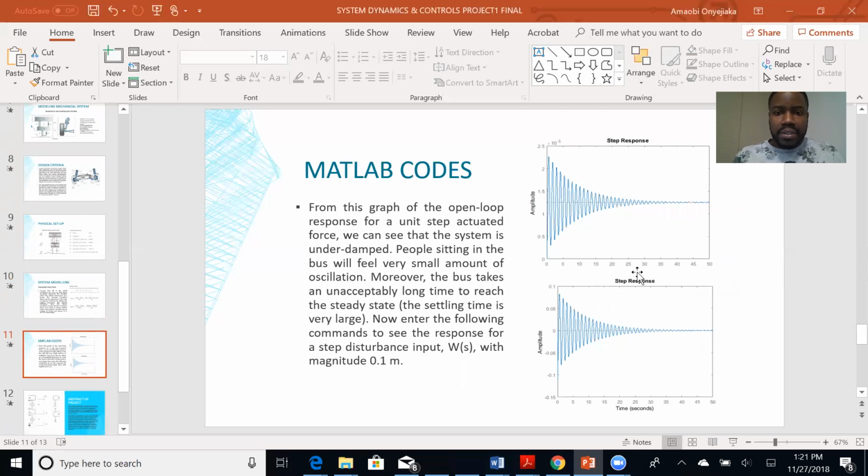This graph here represents a car going into a pothole. As you can see, it does have some vibration, but over time, it starts to even out and become stable again. But this does not necessarily meet the design criteria because it takes entirely too long to stabilize. It takes approximately 35 seconds for the system to stabilize, and based on our design criteria, we want to get all this within 5 seconds. So we have a long way to go to achieve that.